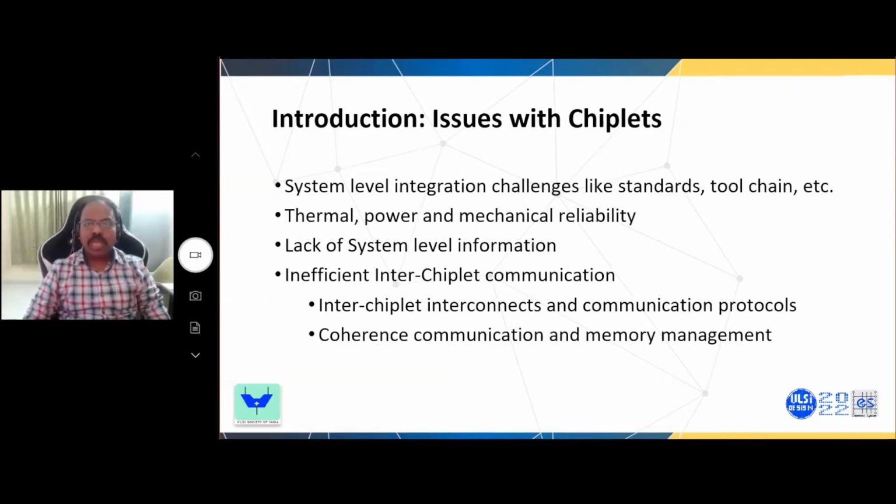Finally, communication within a chiplet architecture is quite different from monolithic dies, since different chiplets can be manufactured using different technology nodes. Also, communication between the chiplets is significantly impacted by the inefficient interconnects that are currently available. These interchiplet communications can lead to different challenges like asymmetry in accessing data or asymmetry in memory access latency, or long latencies and long energy when multiple threads are spread across multiple dies in the system.